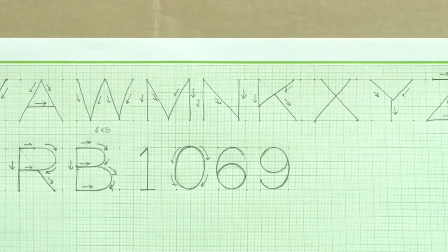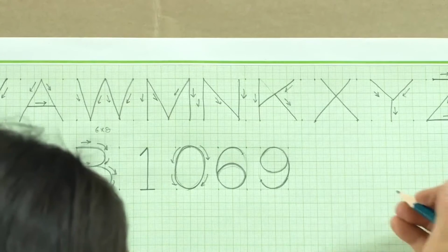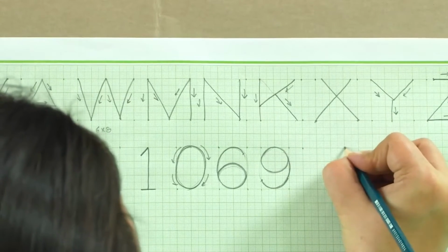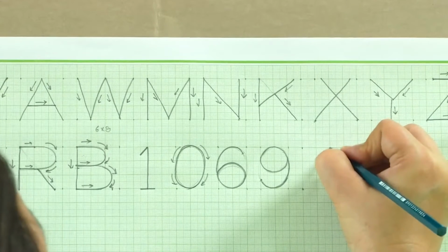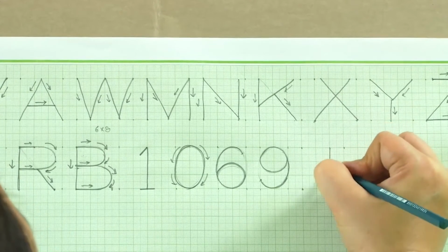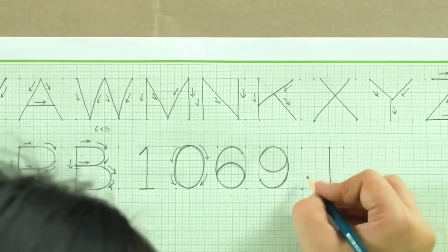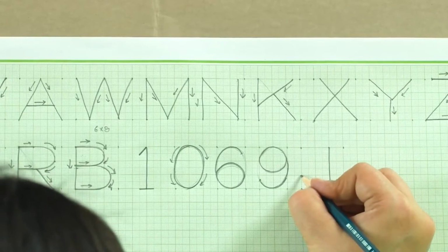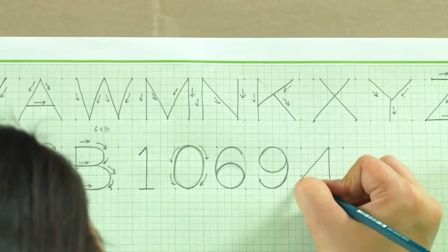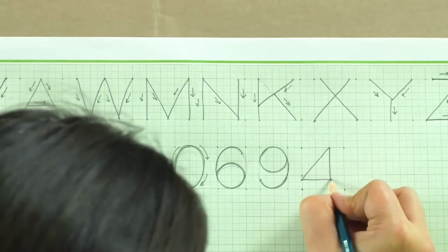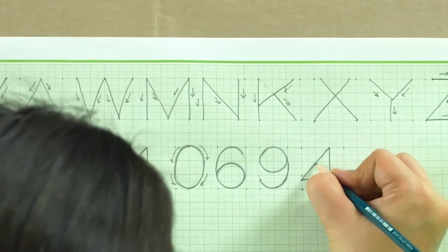So, that is 9 for us. Again, we have this 4, which is a 5 by 6 unit, but the vertical line of the 4 is drawn at 4 units. So, 4 units, and from the bottom we leave 1.5 units here, and this horizontal line will go all the way up to 5 units. So, that is how the 4 would come.